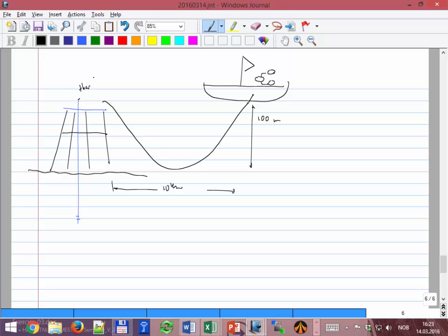Because it's 10 kilometers, I have frictional losses, the liquid is very viscous, and then I have 100 meters that I have to overcome to go up. So how is it possible? In reality, you don't use just the stream, but collect all the production from all the wells, and you have a booster pump that is taking all the production of all the wells and pumping it further. And this pump makes sure that P at the wellhead stays all the time at 7 bar. Okay, so this is a booster pump.